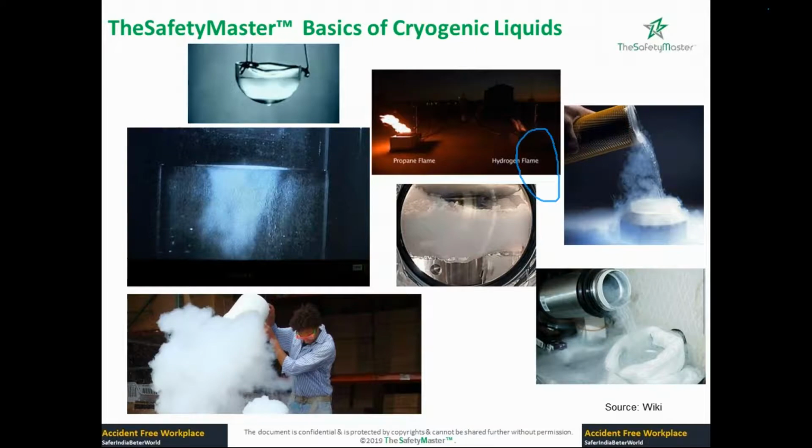If you ask me, with high temperature, certain losses might increase a little bit if your vacuums are not proper, but that is all taken care of. The issues with temperature are something else. In an air separation plant, if the air temperature is high, your production will be less, because the lower the temperature, the denser the air is.